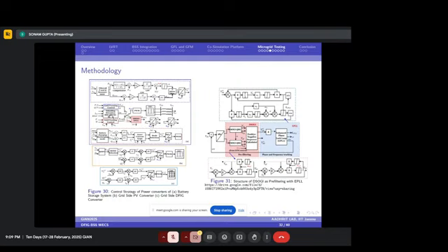So here, when the islanding is detected, it is in the grid forming mode. Otherwise it will remain in the grid following mode. And here we have replaced the basic PLL with the dual second order generalized integrator, which is integrated with the enhanced PLL. That will be implemented in this particular methodology.